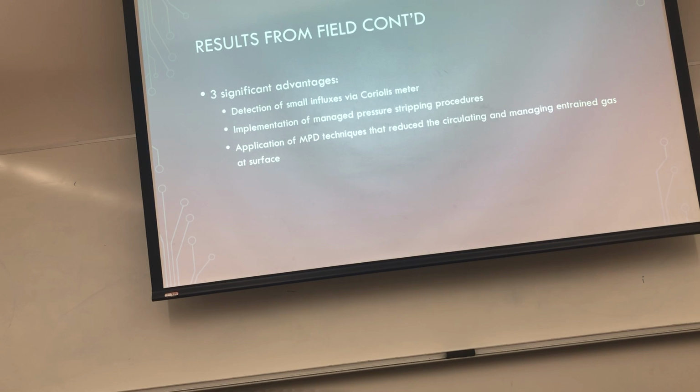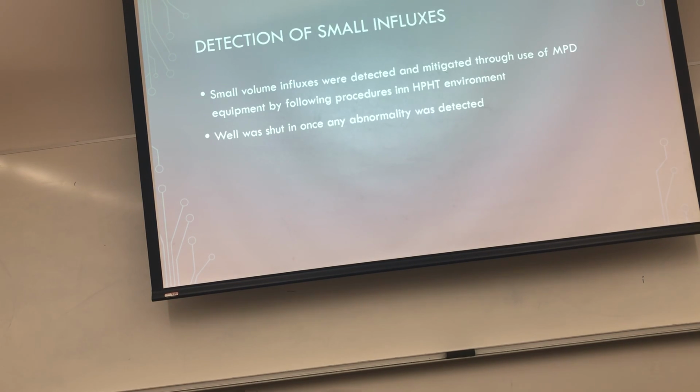We found three significant advantages. There's a detection of small influxes via the meter, implementation of managed pressure stripping procedures, and also an application of MPD techniques that reduce the circulation and manage entrained gas at the surface. So when they started talking about this detection of small influxes within these high pressure, high temperature wells, we found that small volume influxes were detected and they were mitigated through the use of the MPD equipment by following procedures in a high pressure, high temperature environment. The well was shut in once any abnormalities were detected.